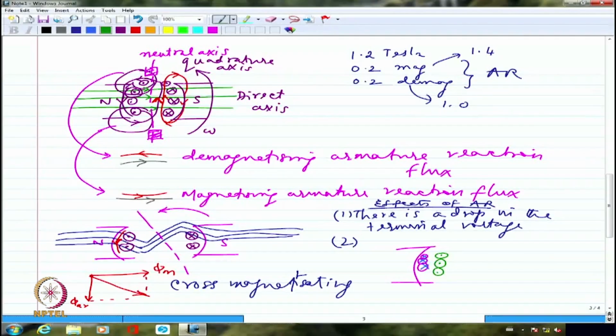That's all. So they will be connected in series with the brushes themselves, normally. If I am carrying only 5 ampere of armature current, I want the compensating winding also to create a flux corresponding to only 5 ampere. So I don't want them to carry a constant current, I want them to carry whatever the armature current is, exactly. So it will be connected in series with the brushes, normally.